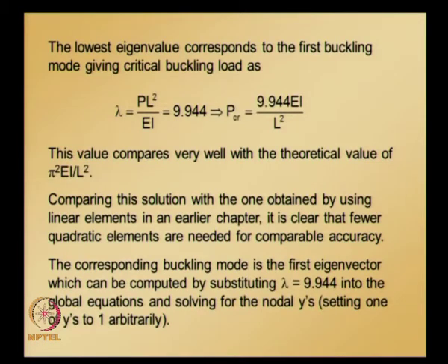The corresponding buckling mode in the first is the first eigenvector, which can be computed by substituting lambda is equal to 9.944 into the global equations and solving for nodal y values.